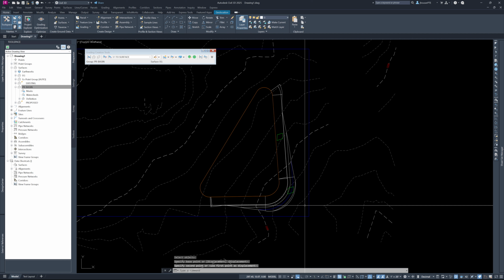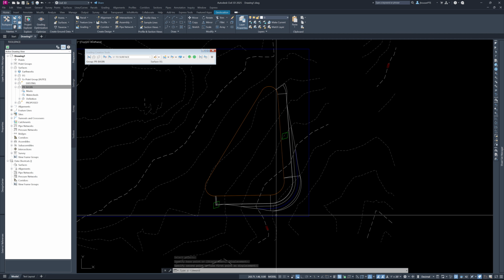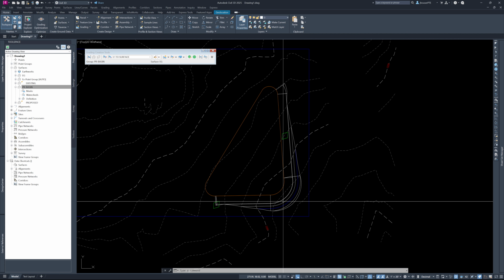So right now, that looks pretty good. We're getting close to the property line. We don't want to be too close to the property line. We might even be able to move that a little bit farther to the right. We need to make sure we have our required distance from the property line for our grading, which I think is probably 5 feet. So we're somewhere around in there now. Okay, so that's great. That's our first grading object there.